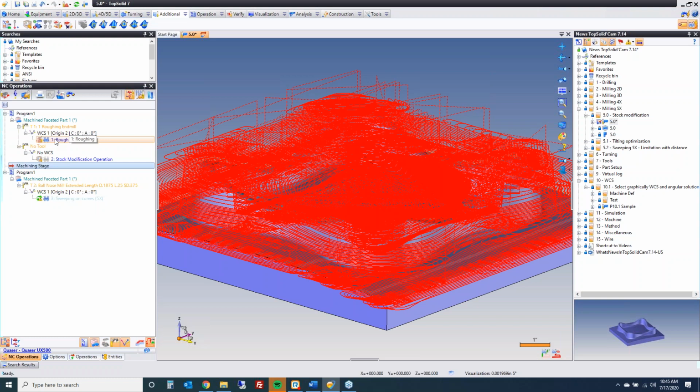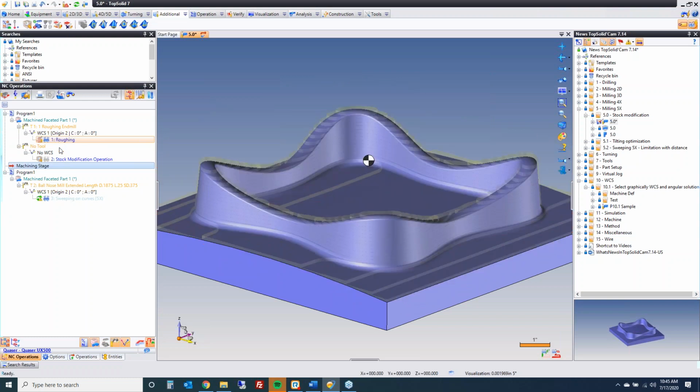But if you were updating the stock through roughing, because you made those little tweaks, the software during a recalc would want to recalculate the stock update. Whereas doing it this way, this is a dumb model. You're saying this is good enough moving forward to everything else. So you're saving a significant amount of time potentially on that update.